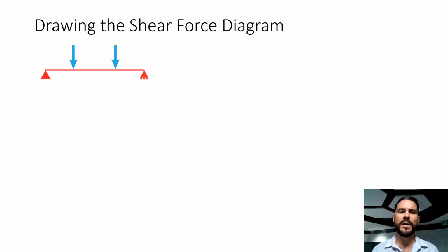All I mean by that is if we've got 0.5 of a meter from each of the ends of our system, I don't know how you want to draw that. If you've got enough room on your paper to draw the 1.8 meters as 180 millimeters, you can, and then the 0.5 of a meter would end up being 50 millimeters. However you want to work your scale, it's really helpful if you get it in scale.